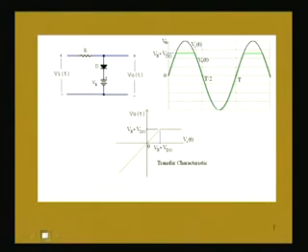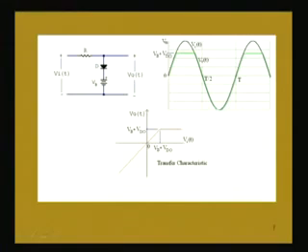So, now before going to another circuit, again let us consider the same circuit, and one important characteristic let us discuss, that is transfer characteristics. So, transfer characteristics is basically a plot between the output voltage and input voltage. You have to be careful because both the axes are involved, that is input voltage we plot in the x axis, output voltage we plot in the y axis. We have to now plot V naught versus Vi, that is called a transfer characteristic.